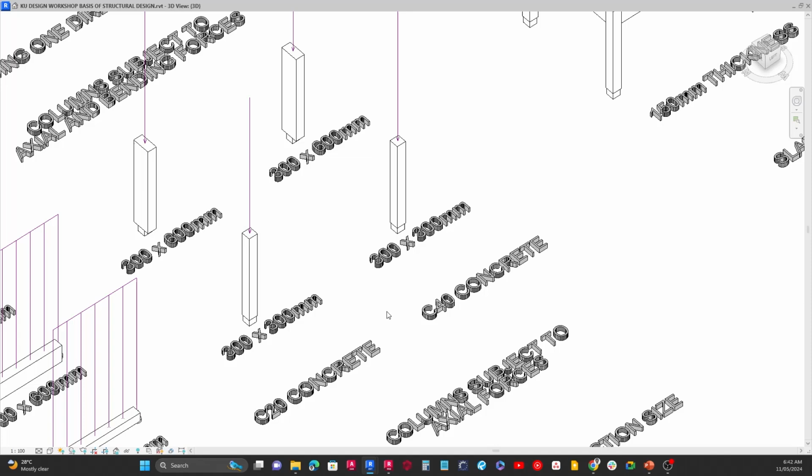Now basically the material does not actually determine how much the column can take, but more or less the section size. Because it's a compression member, it's going to require you to increase the section size rather than increase the material. Although sometimes the higher material can take more loads, most of the time it is ideal to increase the section. Like I mentioned earlier, choosing a higher material may be more costly.